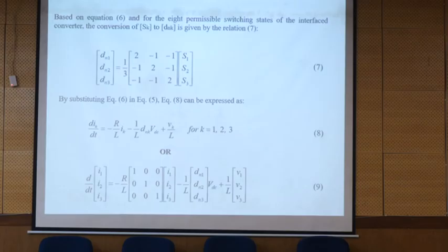We use it not for continuous operation but for the starting operation. When we need a fast dynamic reaction, the capacitor reacts fine, but when we have big changes, the energy that can be discharged is not enough to have a big impact on the stability of the network. This is the problem.